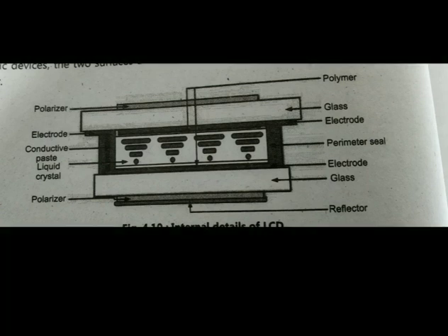When the electric field is turned off, the molecules relax back to the 90-degree twisted structure. This is referred to as a positive image refractive twisting mode. Carrying this basic technology further, using an LCD having multiple selectable electrodes and selectively applying voltage to the electrodes, a variety of patterns can be formed by using these techniques.